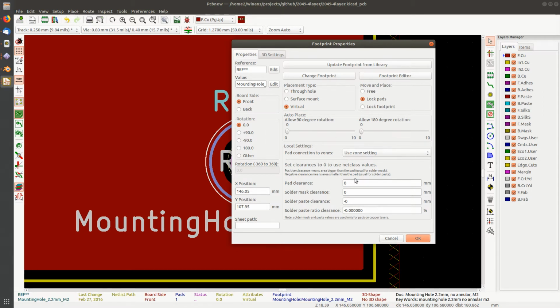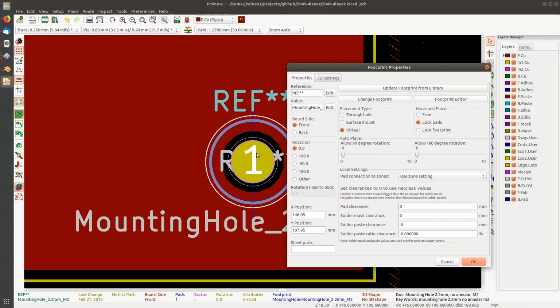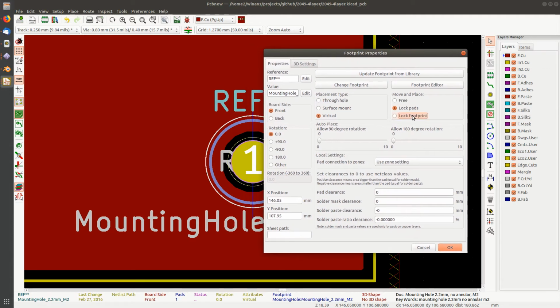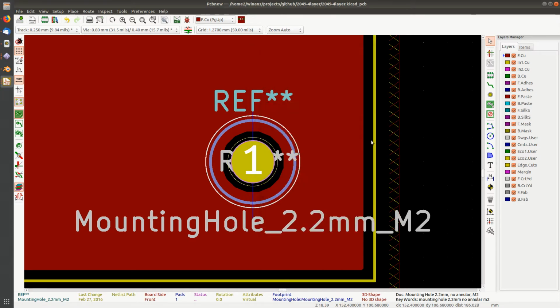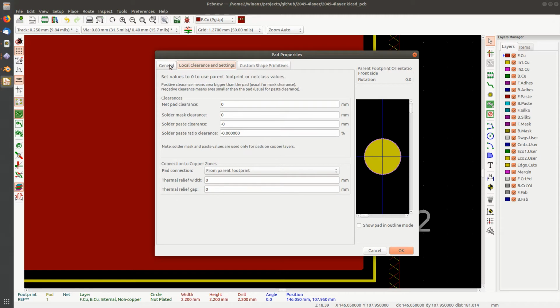But as you get into more advanced design, you need to understand the difference between editing the properties of one footprint pad and the properties of the entire part. In this one example, the two are very, very similar. In this particular editor, you can lock the footprint. You can't do that if you go over here and edit one single pad. I cannot lock the entire footprint from here. All right, there's nothing in here that says let me do that.